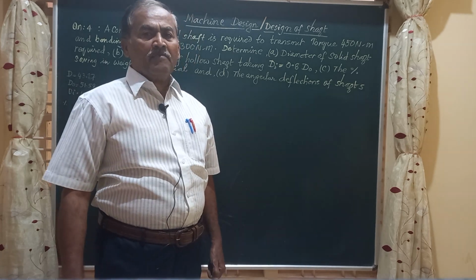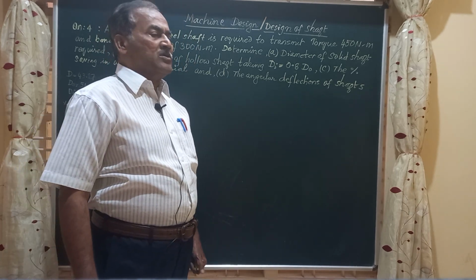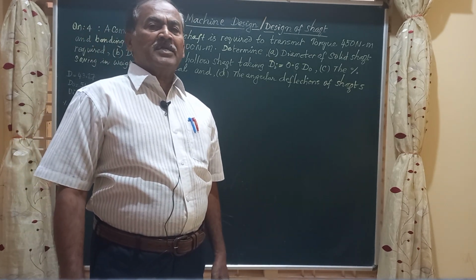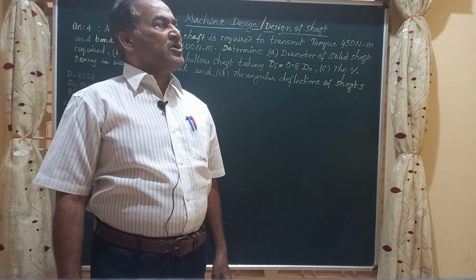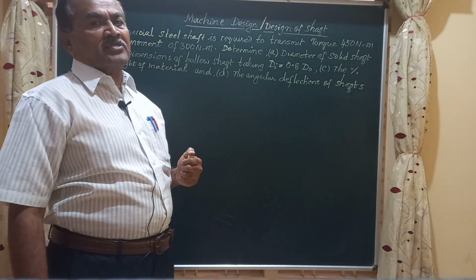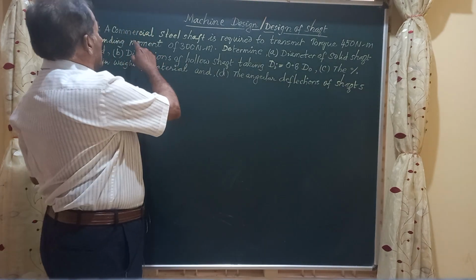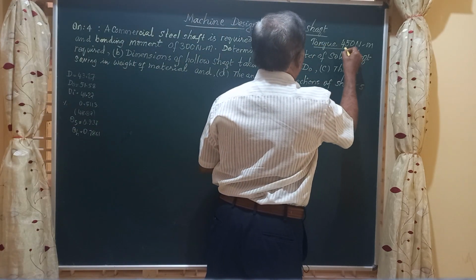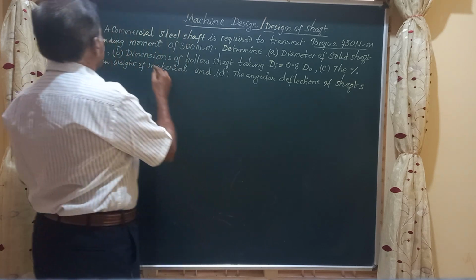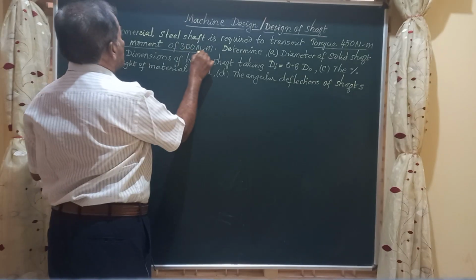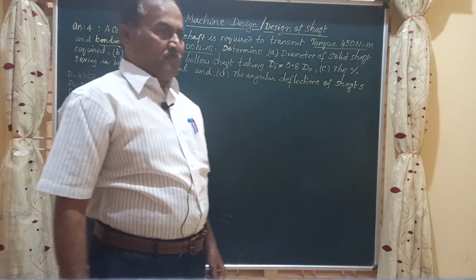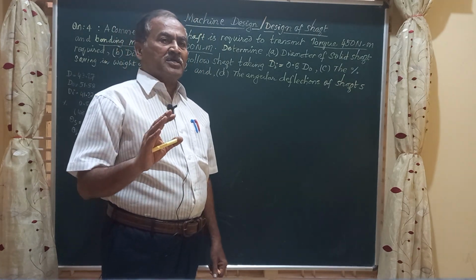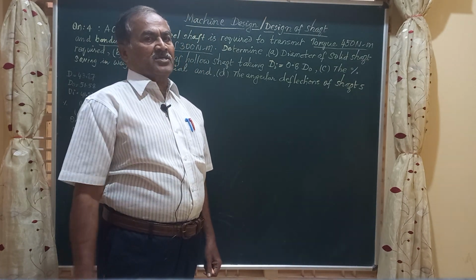Myself Dr. M.H. Annaya, and in today's session we are going to learn a very important problem on the design of a shaft. So here the question for today's session reads like this. A commercial steel shaft is required to transmit a torque of 450 Newton meter and a bending moment of 300 Newton meter. Friends, this is a clear indication that the shaft is subjected to combined bending and torsion, and